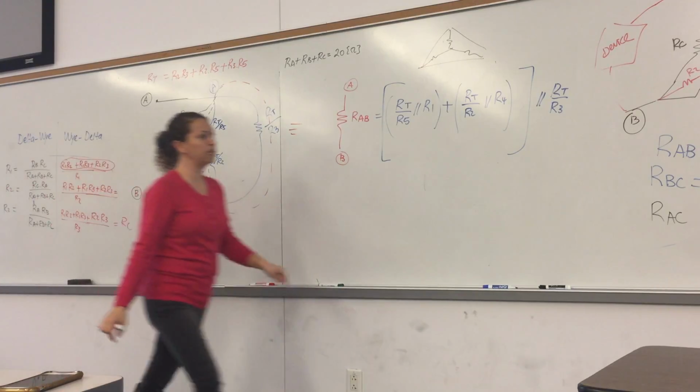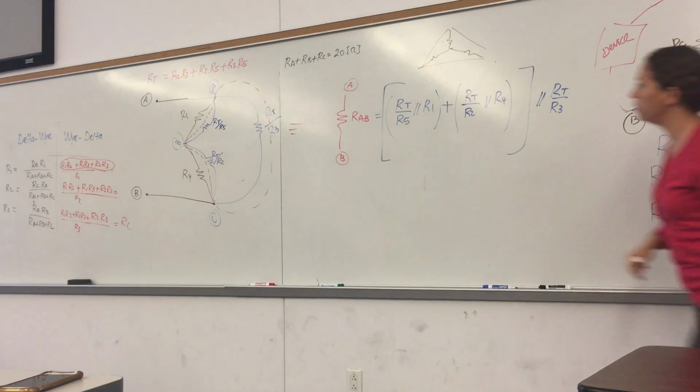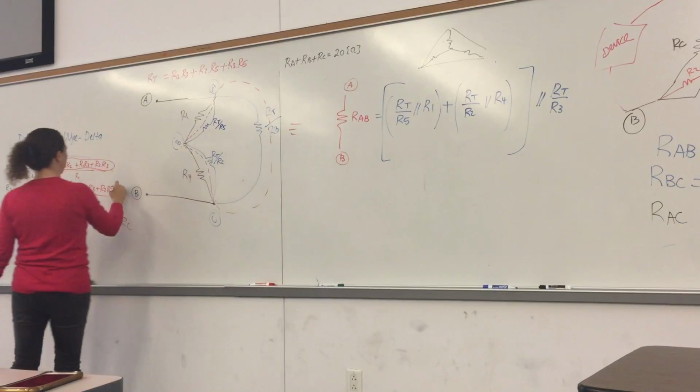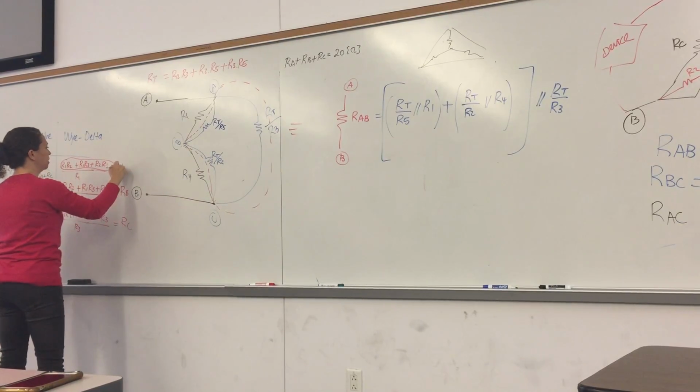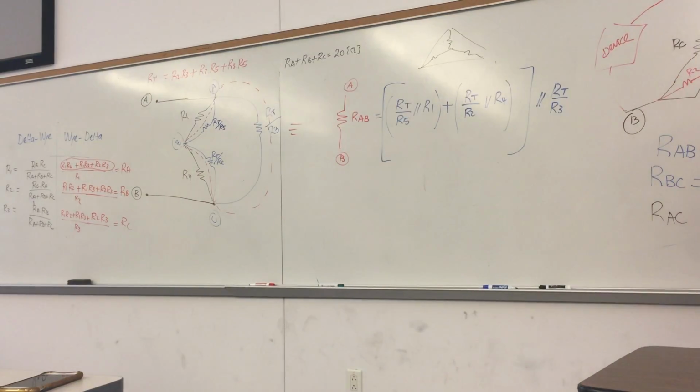So when you are dividing by R2, R2 is connected to B, right? So the resistance divided by R2 must be the one that's not including this. So it's A and C, so that's RB. And the resistance that you get by dividing the total by R1 is right across this, that's RA.